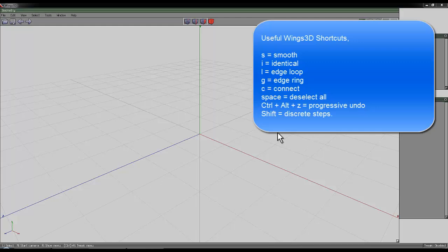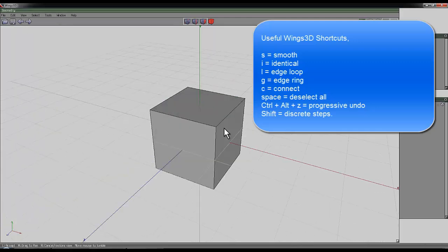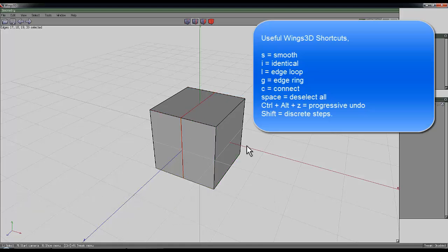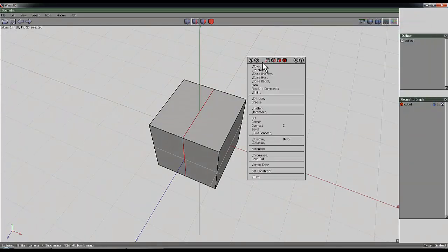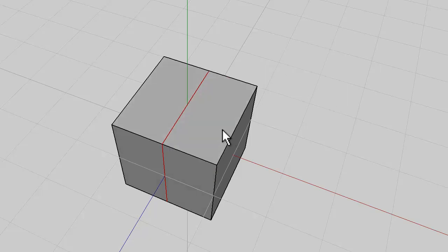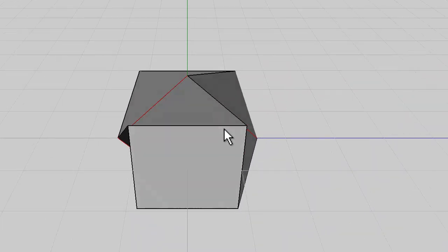Okay, so this is going to be quite involved, so I'll just get straight on with it. Right click, you want to start with a cube. Use the line selection tool, select any one of these edges, use G and cut it so you've got a line in the middle. Notice which axis runs through the middle of that loop, because that goes all the way around the cube. You want to rotate that, and holding the shift key down, it wants to go 45 degrees. It doesn't matter really which way, just remember which direction you rotated it 45 degrees.